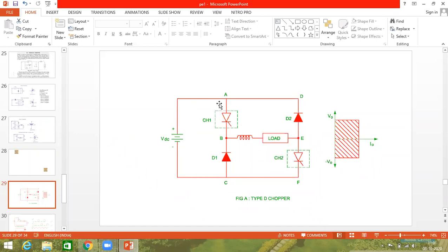First, chopper CH1 should be on. Case 1: CH1 is on and the load is also connected to CH2, therefore CH2 is also on. So case 1 is CH1 and CH2 on. When the supply is on, the current starts from VDC plus to chopper 1, from chopper to inductor, the inductor energizes, and from inductor to the motor, motor to chopper 2, and from chopper 2 to VDC minus. Is it clear? During this condition, the motor accelerates, develops kinetic energy and rotates in the forward direction.